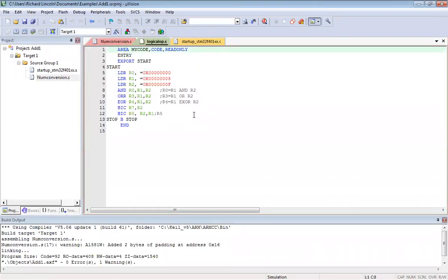Okay. So similarly here, as I told you, we have these values in R1 and R2, and we are going to do an ANDing operation between R1 and R2. So you can just note down these values, 5 and F. Now you know how it is written, 0 5 and 0 F, and you can do a normal ANDing operation and find out how these are performed. So can someone verify for me how this ANDing operation is done? I want you to verify the result for me.